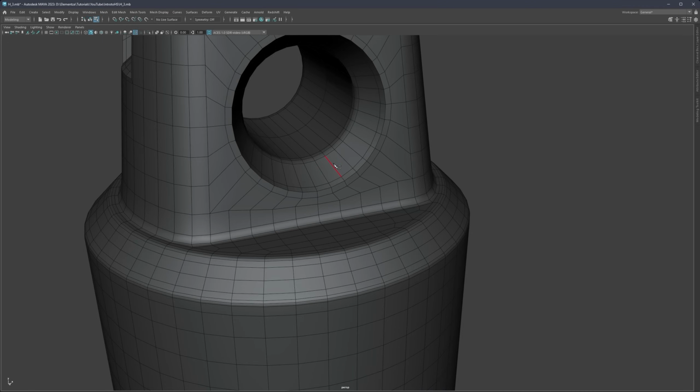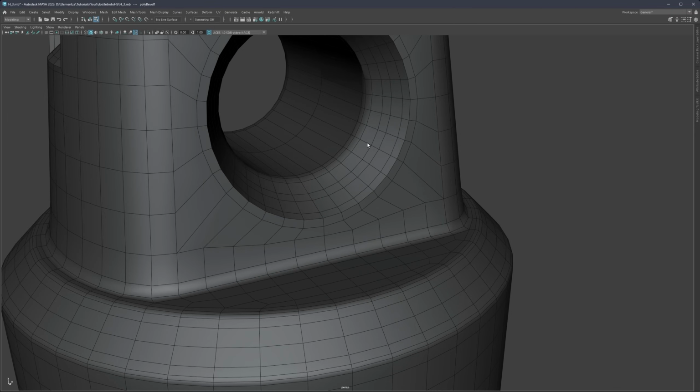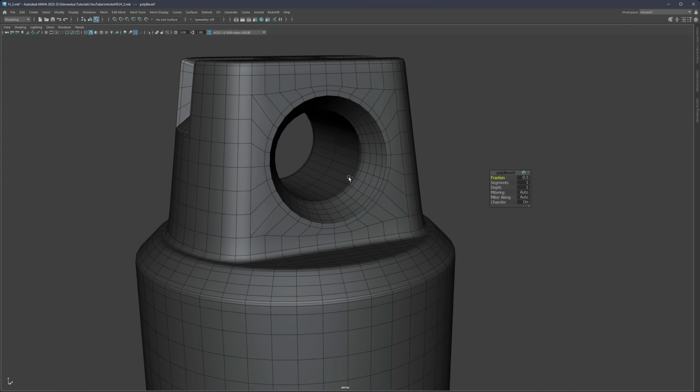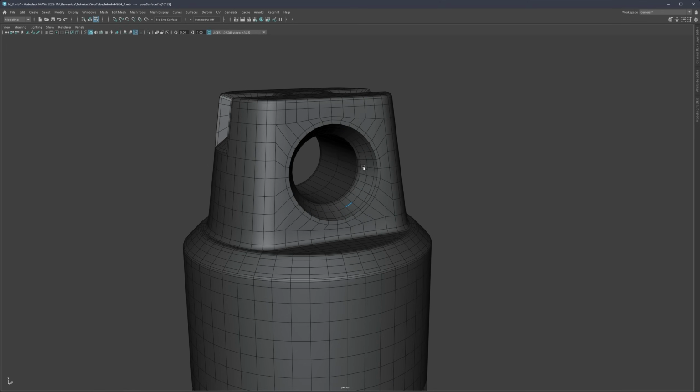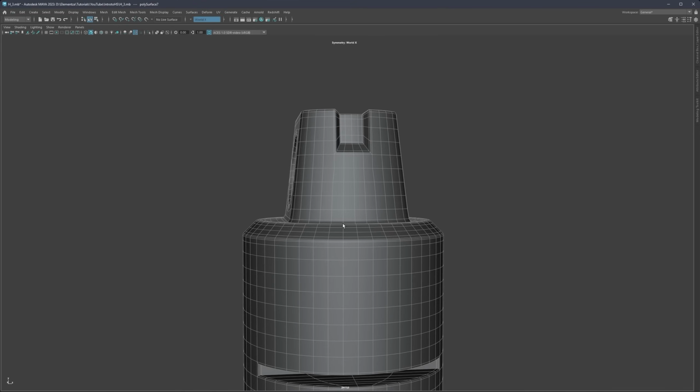All right, so let's continue with what else we can do. For example, let's go here with the multi-cut and create a small bevel. Small bevel, Control B, Q to confirm, go to face mode, and then extrude face, a small extrusion. I'm not sure, let me undo this because I would like to do this with symmetry on the Z axis.